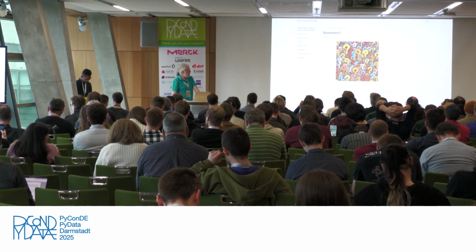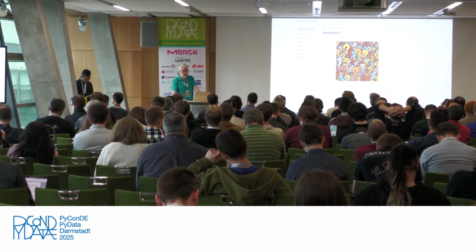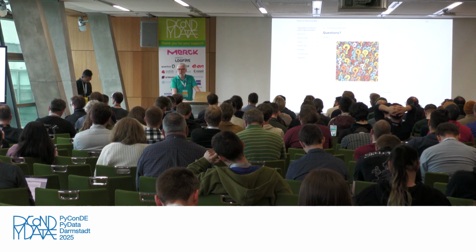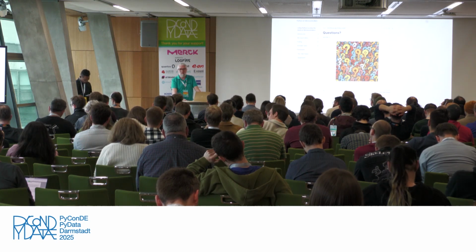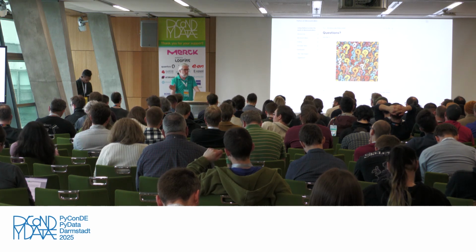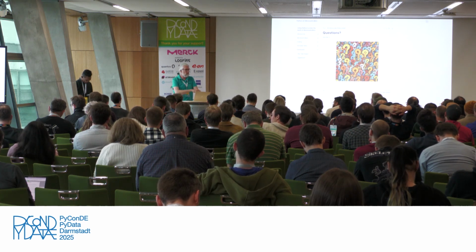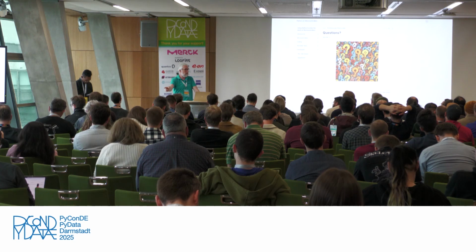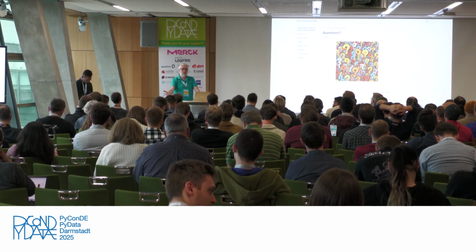And probably the Pico W, the Raspberry Pi version, is by far the easiest thing. You can't break it. You attach it to your computer. It shows up as a mass storage device. You copy the MicroPython firmware on it. Afterwards, it will reboot, and then you have a MicroPython device.